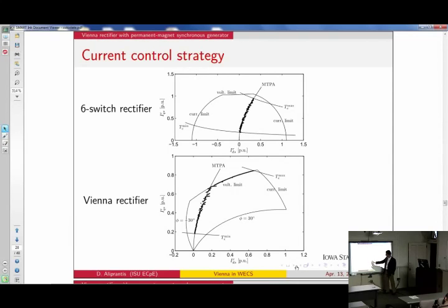And as you go up, you're going to hit the voltage limit, unfortunately. Then you cannot keep going on the MTPA as you do here, and you need to switch from MTPA to another voltage limit curve. You're limited by your voltage limit, but you can still get the torque all the way out to the maximum torque that you need. You can still operate the thing. You're just not going to be on the MTPA forever due to the limitations of the inverter.